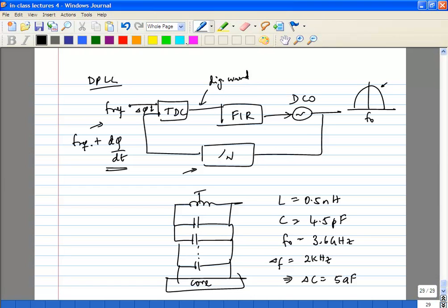Okay, in those cases, you obviously want your filter at this point. You want your signal, your phase signal, to completely come through, which means the bandwidth of the PLL should be very predictable. It shouldn't vary that much.